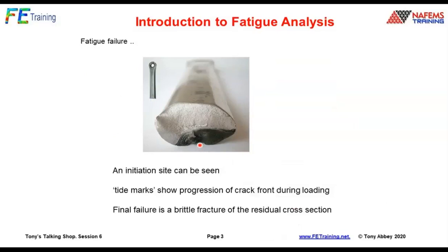We can't really see that initiation site. Go to the electron microscope, maybe we can actually see it there. And the black area is the oxidization or rubbing as we're actually starting to propagate the crack.